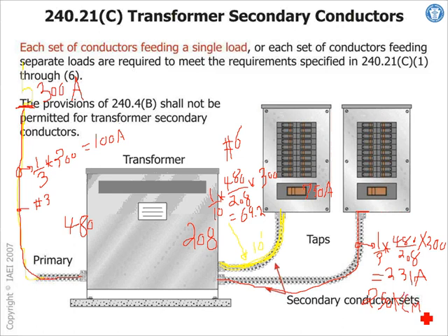Now, there's another tap, that 25-foot tap for the secondary. You see that 10-foot tap? I can make it 25 with no limitation how small the conductor is, as long as it's protected from physical damage, landing on an overcurrent protection device that protects the conductor.